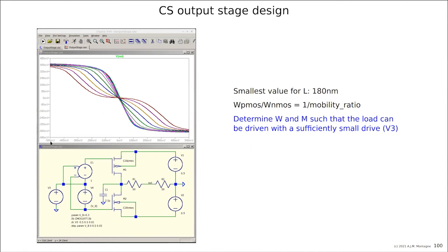So you see, if you need an input swing of 500 millivolt and the thing is completely clipping, you can imagine you will have a huge distortion and you need an extremely high loop gain to get to low IMD. So there is some compromise, of course. So I aimed for this green one, number 1, 2, 3, 4, 5, this one. It looks quite linear when we go through the origin, and for a 320 millivolt output you need about 200 millivolt drive, and then it is fairly non-linear.